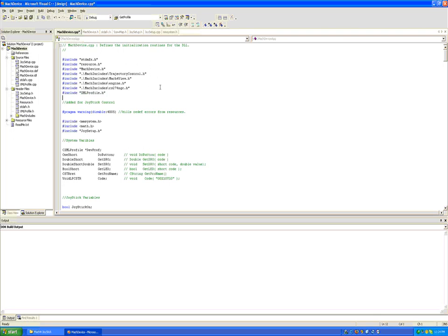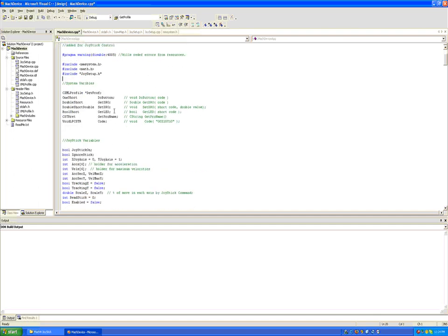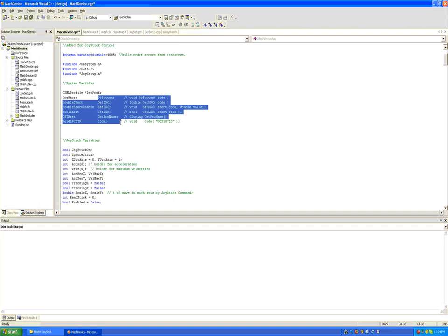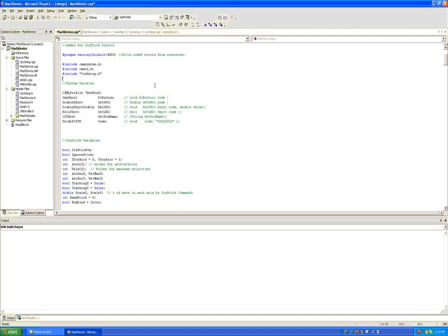Ask questions, yell at me when you have a specific question on a variable or where to find a variable. Most of the variables are stored in the places that I've given you access to. If you wish to get DRO values and so on, use these calls: do button, get DRO, set DRO, get LED, and get and code to send code directly to be executed by Mach 3. All of those functions will work within the context of Mach 3, and it's pretty much invisible to the system.